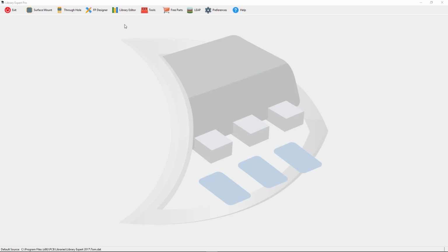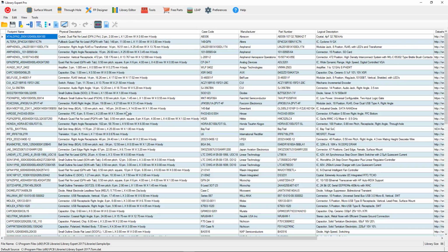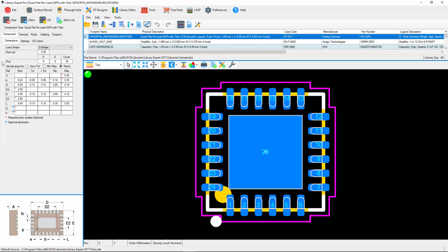This video presentation explains how component dimensions and user preferences work together. The FPX file only contains component dimensions. If we open up an average part, you can see on the panel the component dimensions. And that's the only pertinent thing in the FPX file that's used to actually build the footprint.